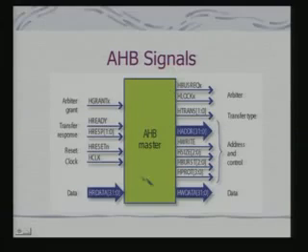So, what are the AHB signals? If I look at these as an AHB master, this is a kind of conceptual model. Any CPU or a DSP can be an AHB master. The whole issue is that the bus interface unit of the AHB master should be compatible with these kinds of signals. Already we have seen that it will generate the request. This is a request to the arbiter. It will get the grant from the arbiter.